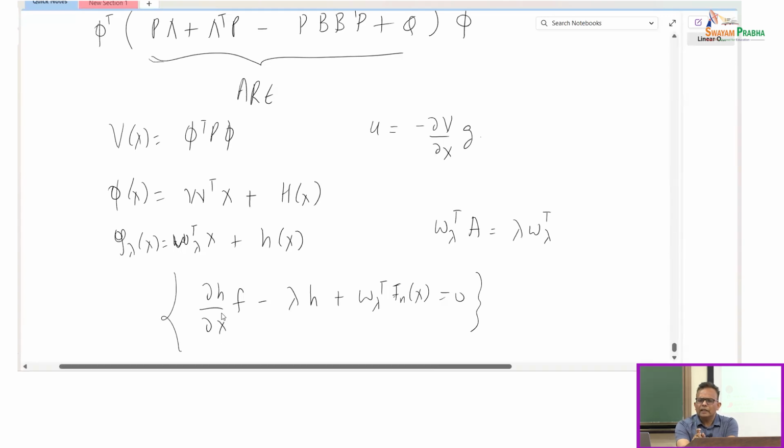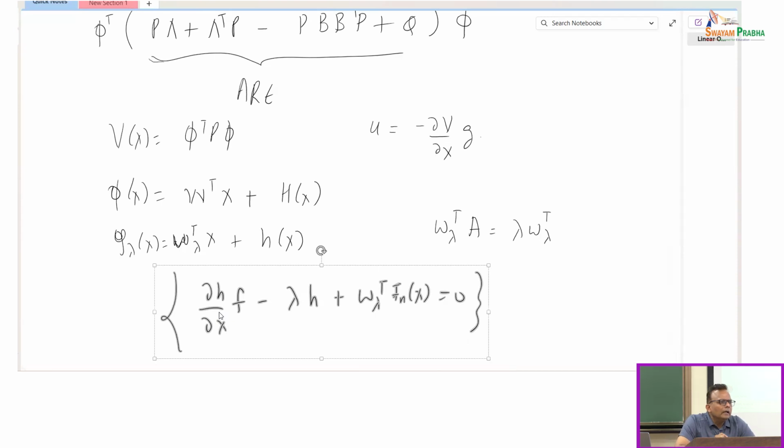Okay? So that way you can overcome some of the limitations of existing Koopman-based control design, especially MPC, which is actually aware of the fact that what are the limitations of that linear model, because trying to construct a global linear model from data is not realistic, or rather it's like a pipe dream, right? So the data is local, so the model will also be, especially because the model is actually finite dimensional. It's not an infinite dimensional model.